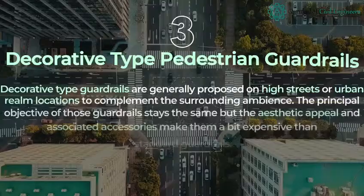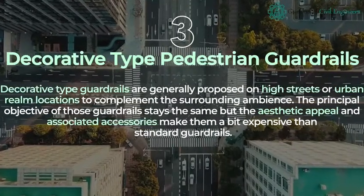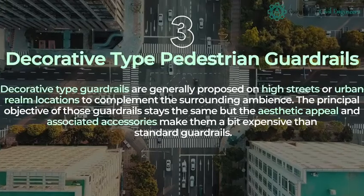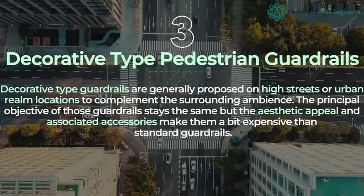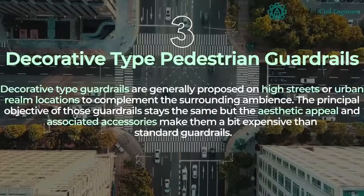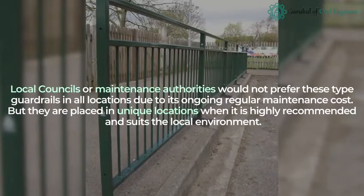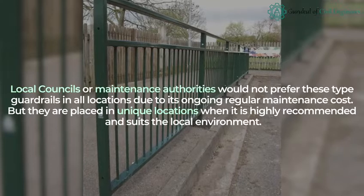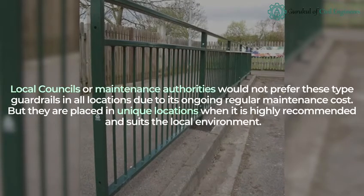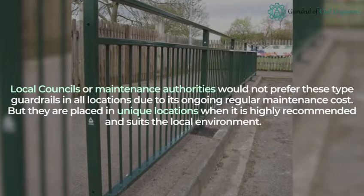Decorative type guardrails are generally proposed on high streets or urban realm locations to complement the surrounding ambience. The principal objective of those guardrails stays the same, but the aesthetic appeal and associated accessories make them a bit more expensive than standard guardrails. Local councils or maintenance authorities would not prefer these type of guardrails in all locations due to their ongoing regular maintenance cost. But they are placed in unique locations when it is highly recommended and suits the local environment.